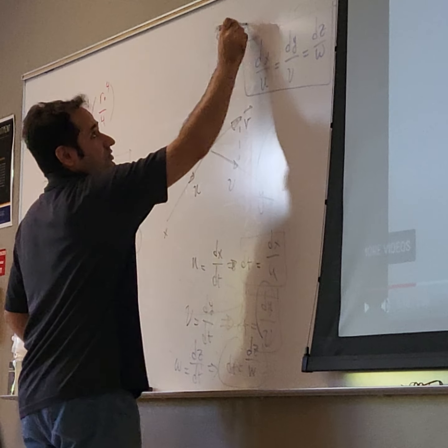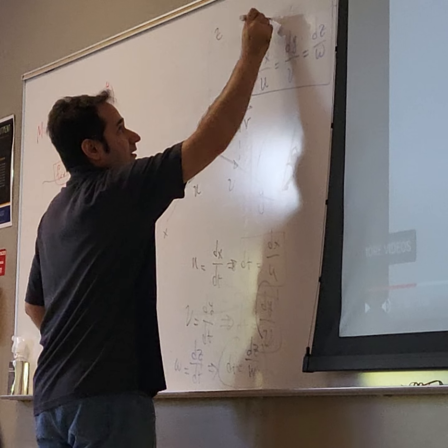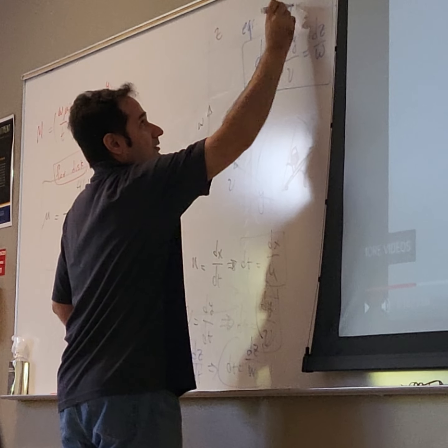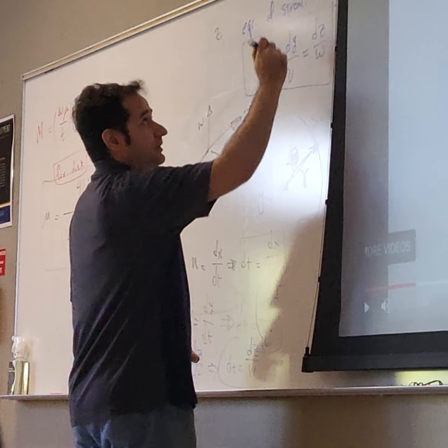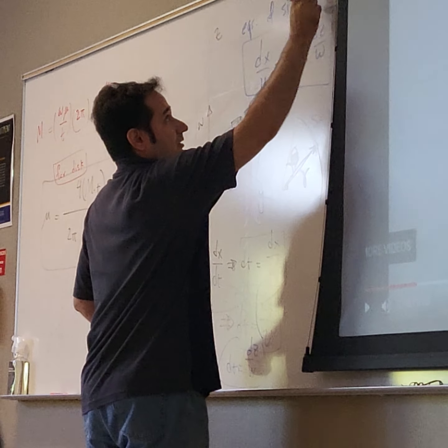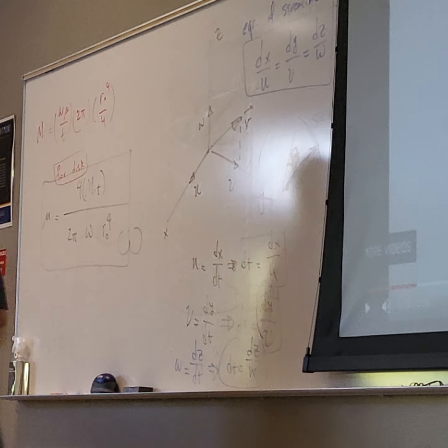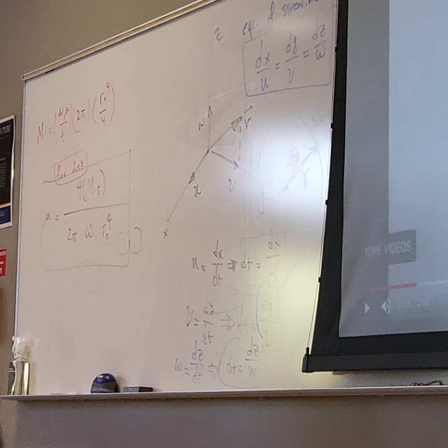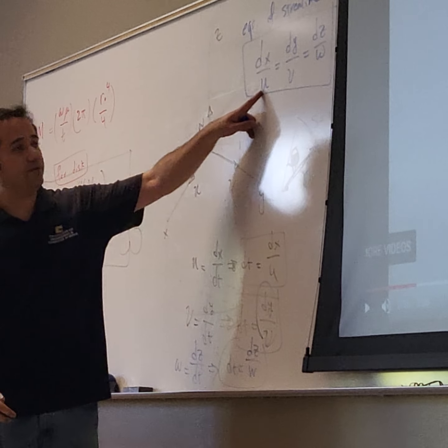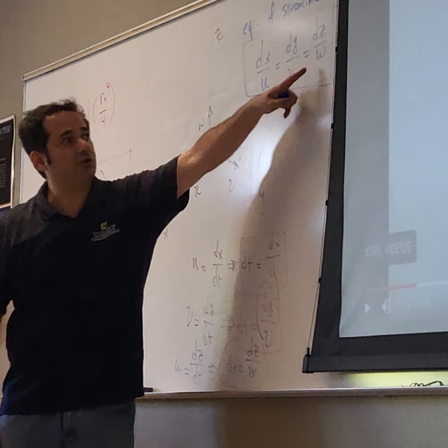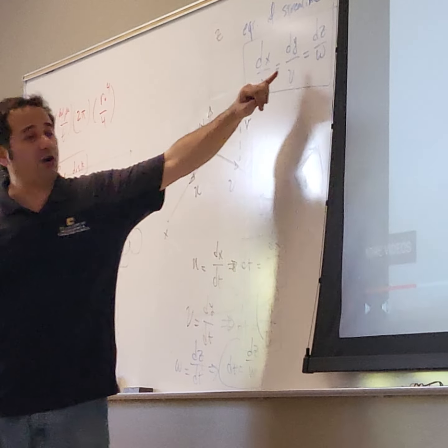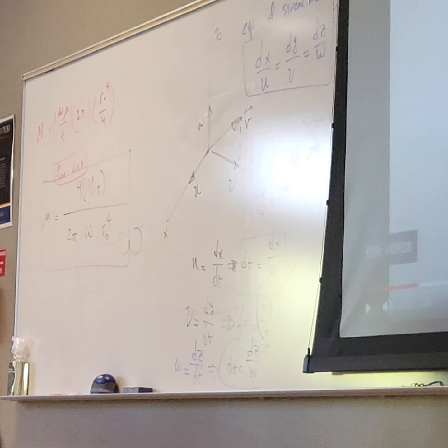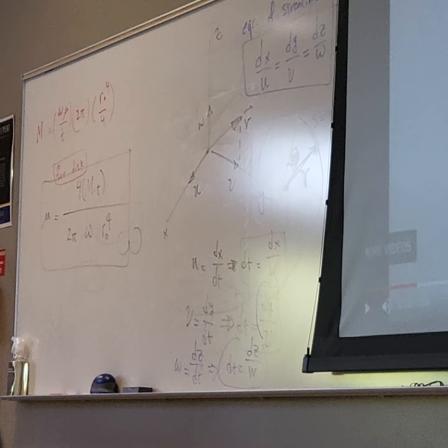We call these the equations of streamlines. I'm going to give a question in the midterm exam, the first midterm exam, from this. It's streamlines. So what are the streamlines? Mathematically, if I give you the velocity field, u, v, w, in terms of x, y, z, this is an ordinary differential equation. If you solve this equation, how do you solve it? You integrate both sides, right?